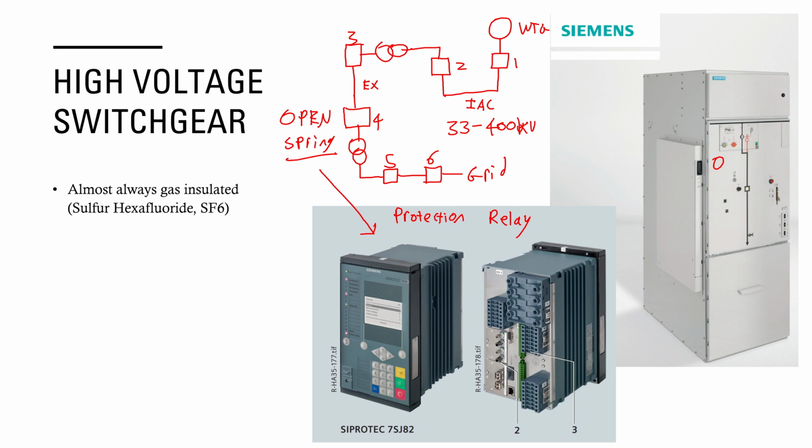In principle, you could use vacuum switchgear, which is widely used in the grid, for example. After all, vacuum is a better arc quencher, but for various reasons to do with compactness, that's generally not possible on wind farms.